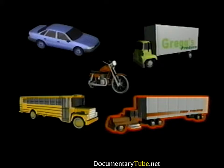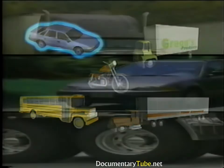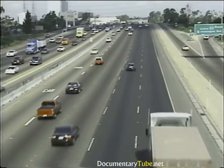In general, the loudest vehicles are in the heavy truck category. As an example, at a distance of 15 meters or 50 feet, a single heavy truck traveling at normal highway speeds can produce a maximum sound level of around 85 dBA. The quietest vehicles are in the automobile category. For the same conditions as the example heavy truck, the maximum sound level of the automobile is around 75 dBA. The major noise sources in vehicles are, for trucks, the exhaust stack, and for all vehicles, the engine and tire-pavement interaction. The sound levels of individual vehicle noise are influenced by how fast the vehicle is traveling.